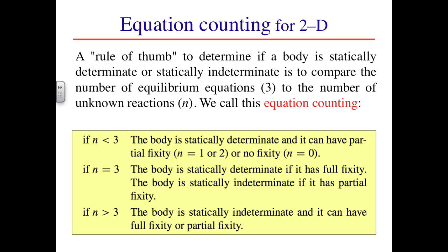If n is equal to 3 and the supports are properly configured to ensure complete or full fixity, then the body is statically determinate. If n equals 3 but the supports are not properly configured, the body has partial fixity and is statically indeterminate.